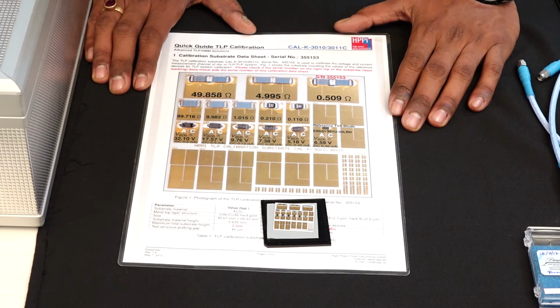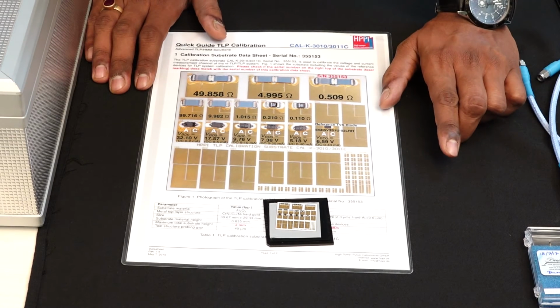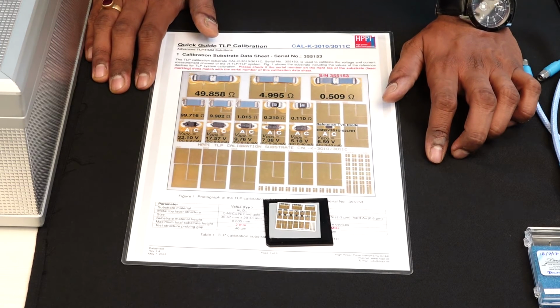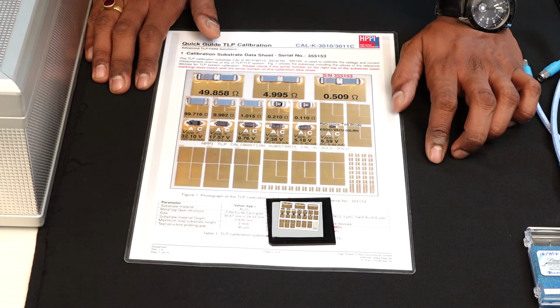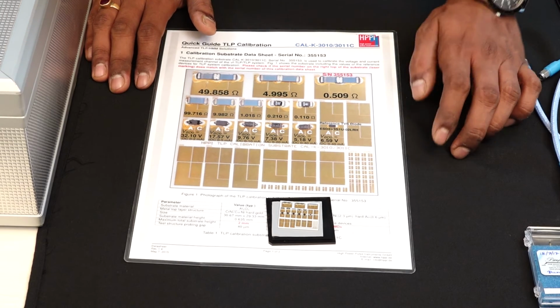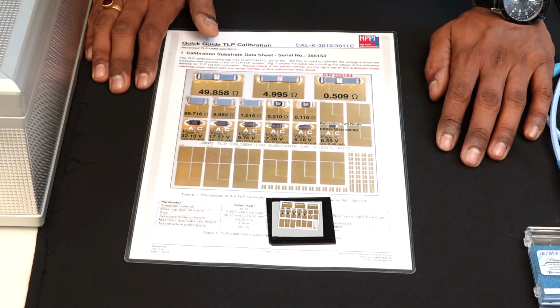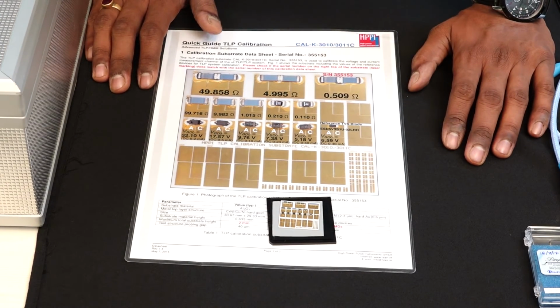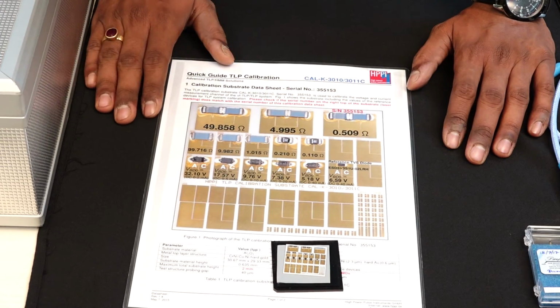These calibrations are important because, first, your voltage and current channel may, for different reasons, have a time lag between them. Say for example, when you are applying a voltage, your current channel might be lagging behind or leading ahead. In that case, your oscilloscope will measure 2 different waveforms which are shifted from each other in time, and you don't want that, right? So for that there's a calibration step called de-skewing. This is the calibration substrate I'm showing, and I'll tell you more of the geometric details of this calibration setup.